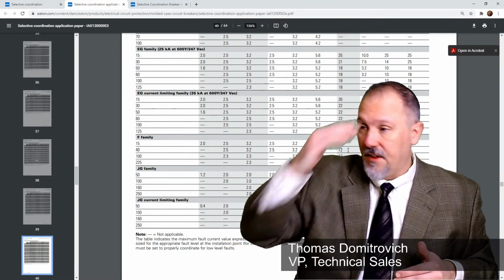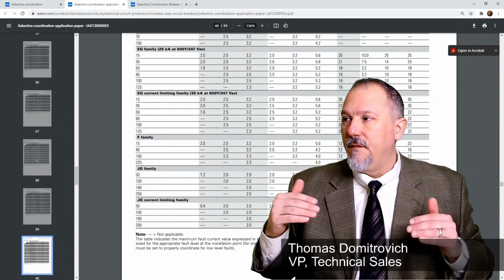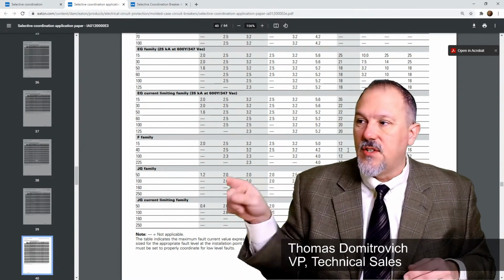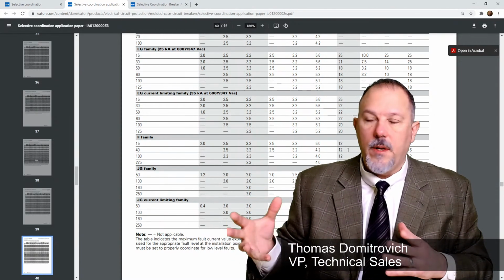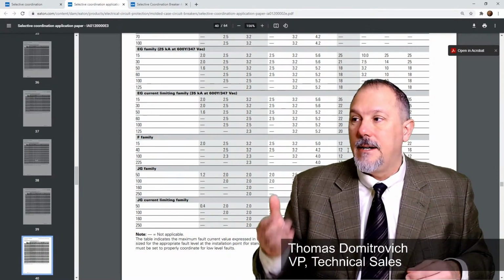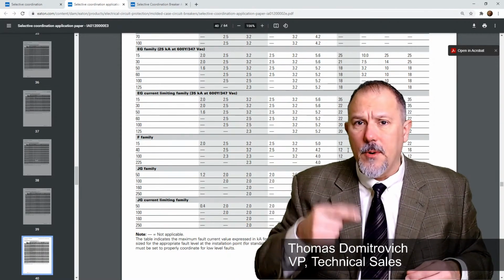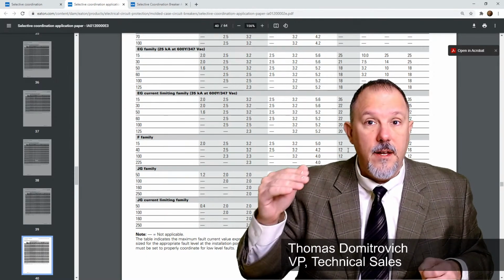Now, you'll say, well, the 15 says 12,000 amps too. The reason they probably broke out the 40 is there's probably a difference somewhere all the way up through the chain in between those two. Or it could just be a frame break. So in any case, the 20 amp breaker would fall under the 40, not the 15 row.